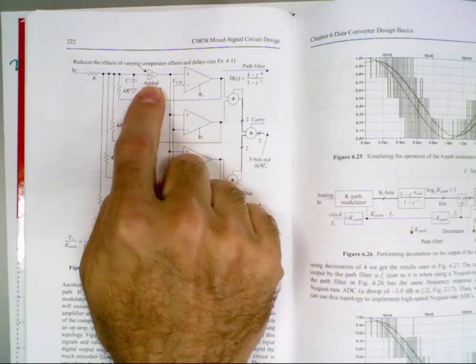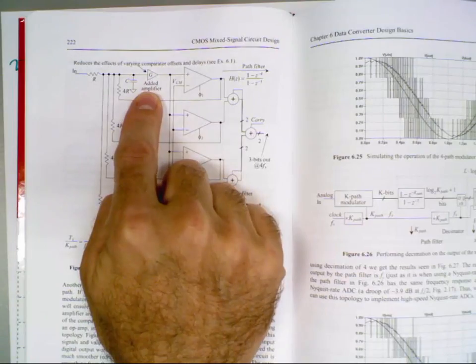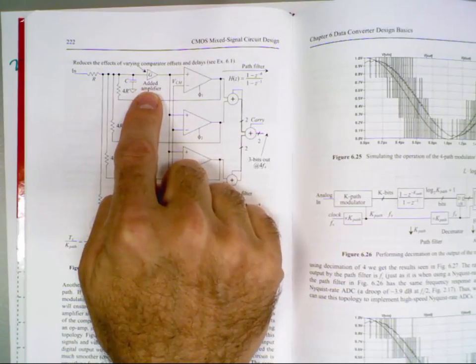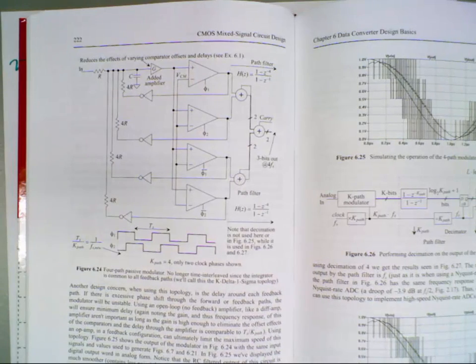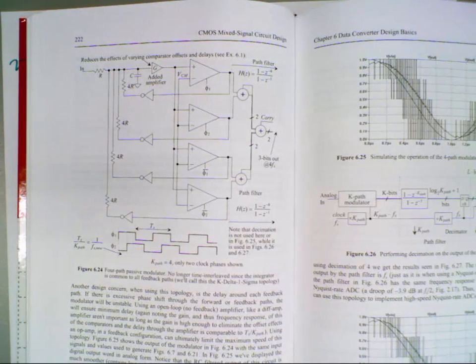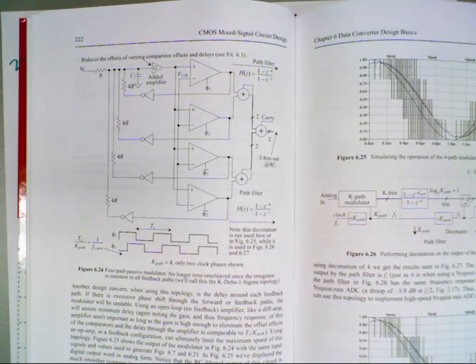No, it doesn't. So what I used here in the sim, I probably used a voltage controlled voltage source, but what you could use is that amplifier I showed you, the self-biased one. That would work fine. The issue with the self-bias is you've got to be careful about the input common mode range not falling within the range that you want.